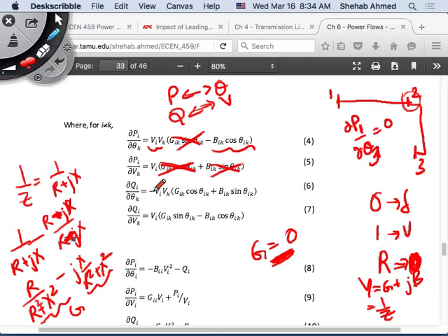But when you solve the power flow problem and you look at the numbers, you need to understand what's happening, right? So at a bus where there's a load, I see a big angle because of this phenomenon. At a bus where you see big changes in angles, you expect to see big changes in real power because there is a strong coupling between real power and angle. But there is no strong coupling between real power and voltage. It exists, but it's not very strong.